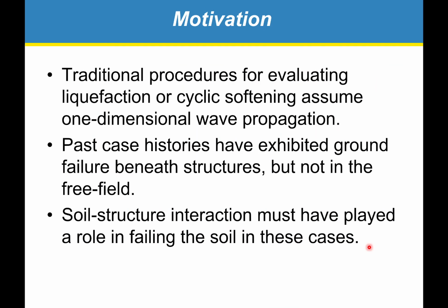So that brings me to the motivation for the work that we're doing, which is a little different from these sort of settlement predictions. The motivation for our work is that traditional procedures for evaluating liquefaction or cyclic softening assume one-dimensional wave propagation. Past case histories have exhibited ground failure beneath structures, but not in the free field.